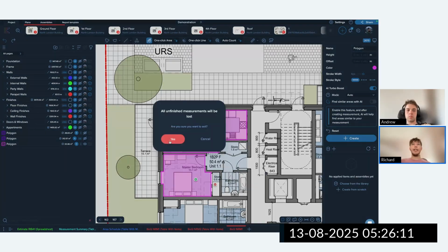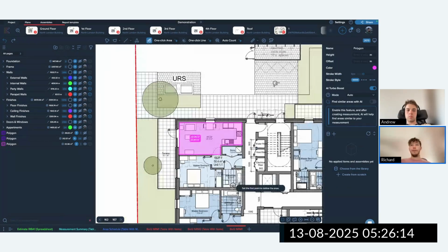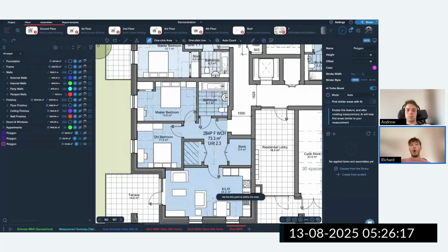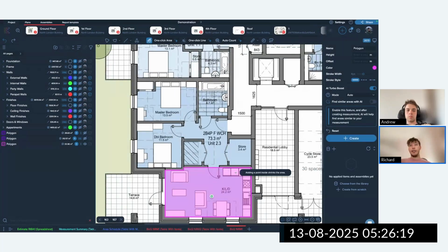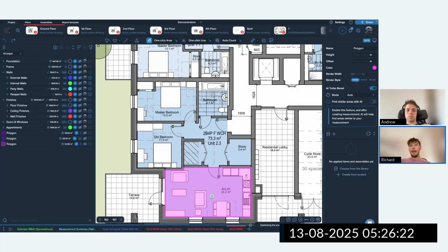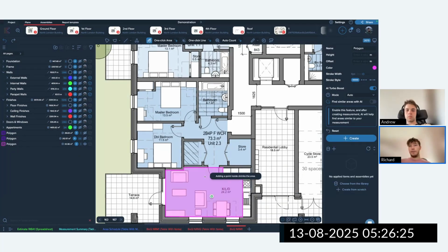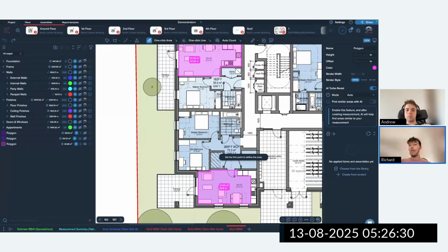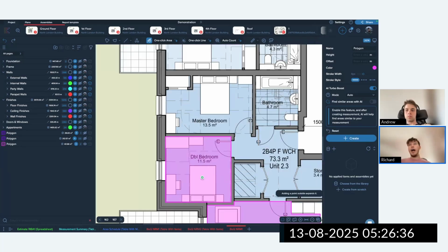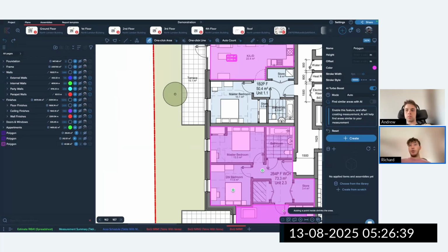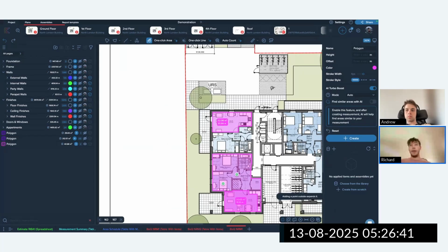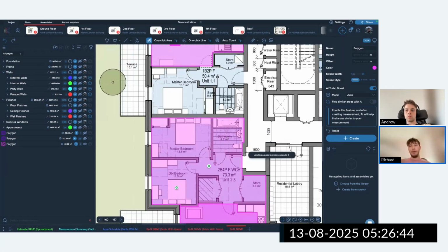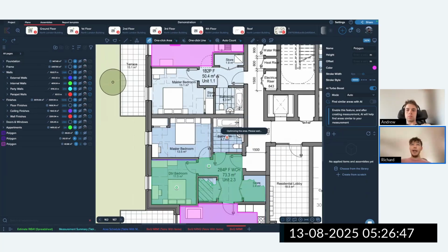In the same way, you can get any really very specific or very complicated measurement. Going back to this example, I can click on top of my countertop, and now Kreo excludes this entire countertop from my takeoff. In the same way, you can get mostly any takeoff. Again, I start from this double bedroom. I have this preview. I make the second click, and you see Kreo goes and measures this entire flat for me. But maybe I want the entire flat without the bathroom because it's a wet area, and I can get it like that in just 2 more clicks.